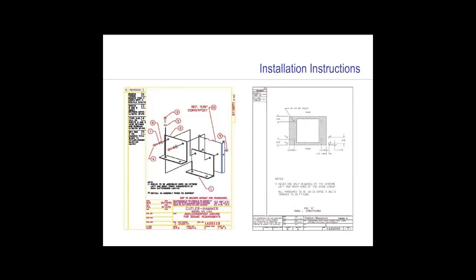Some manufacturers even supply special hardware where seismic qualified equipment is required. This hardware must be utilized to maintain the seismic qualified rating and certificate. It must be noted that although the manufacturer will instruct the design professional and installer as to the diameter and location where the anchorage or attachment should occur, it is up to the locally registered civil or structural engineer to determine the type and depth of embedment of that attachment or anchorage.